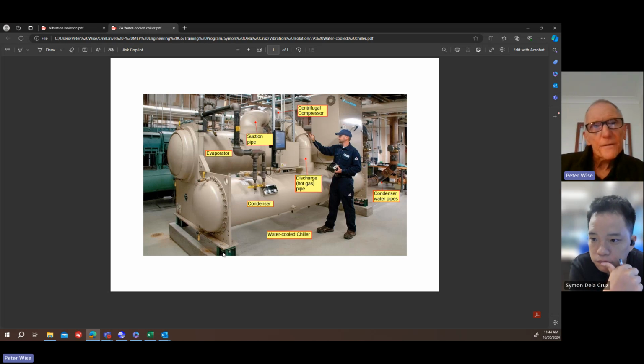In other words, if those springs are open and they haven't got restraints there, and there is an earthquake, the chiller might rock around and actually fall off the mounts, and that's going to break the pipes. You know, it's not going to work. You're going to have a flood in the plant room and the chiller's not working. So, just things to bear in mind.